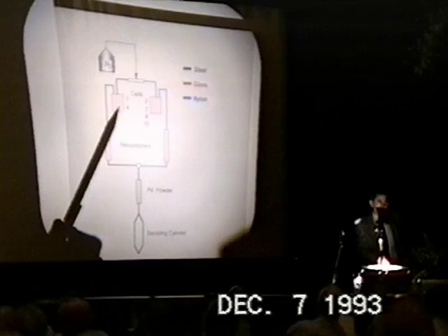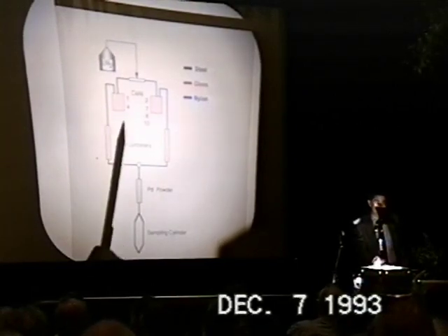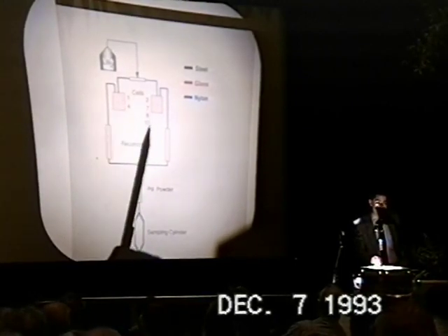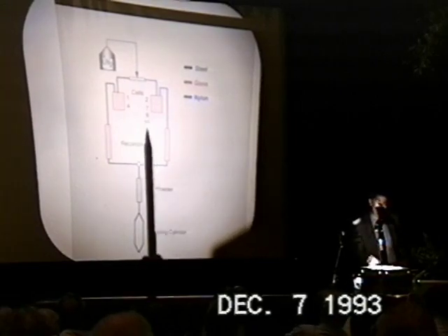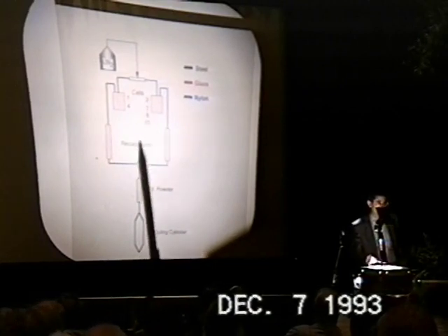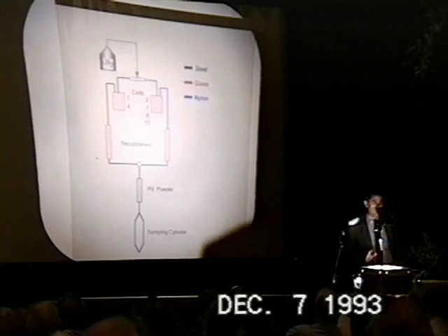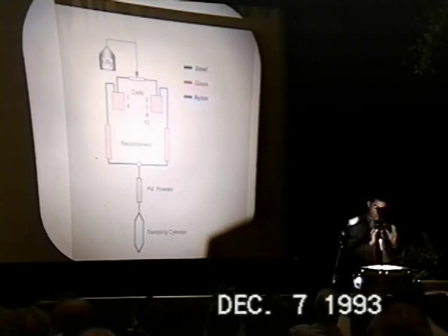Why? We got helium values for cell number 4 that are approximately 1 order of magnitude greater than cell number 1, and for cell number 10, something like 2 orders or more greater than cell number 2, 7, or 8. So it can be permeation. It must be leaks through the joints or some defects of the materials, but not the type of materials.